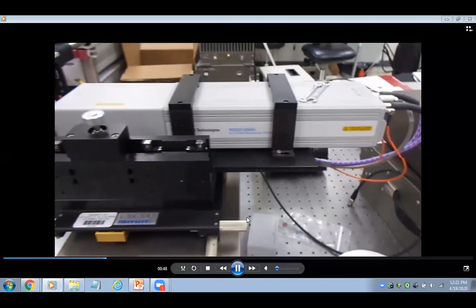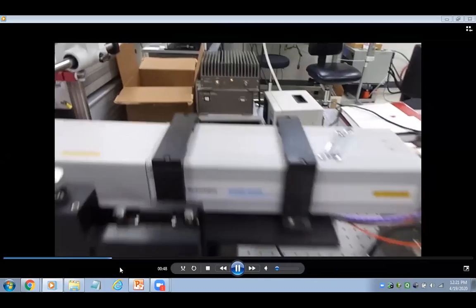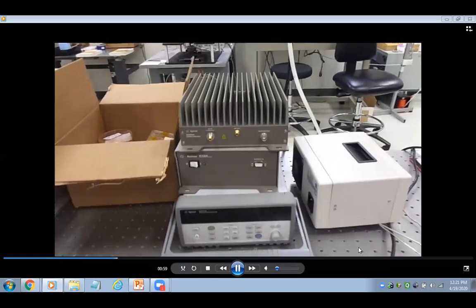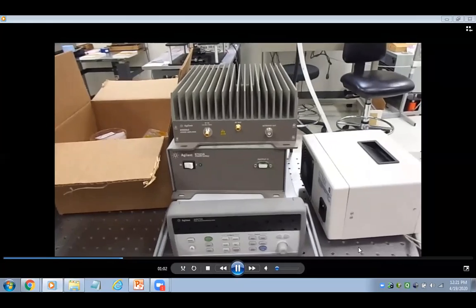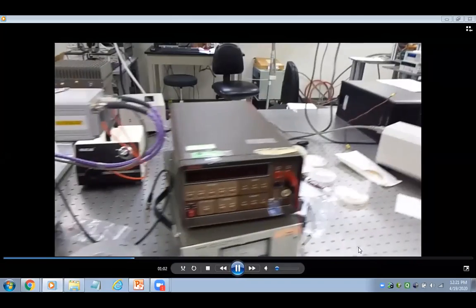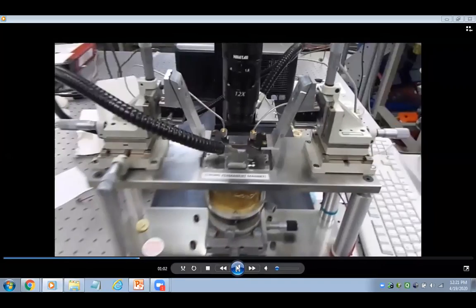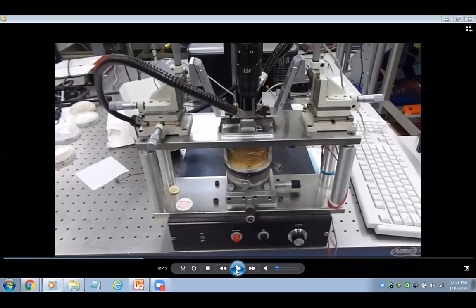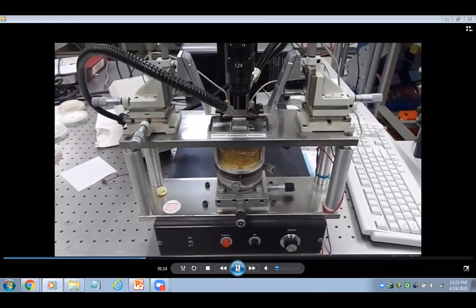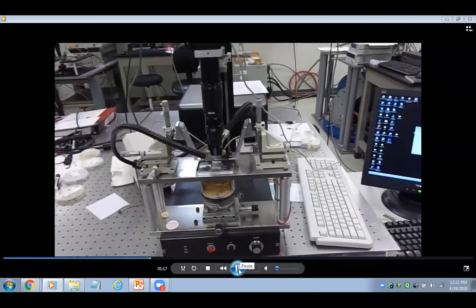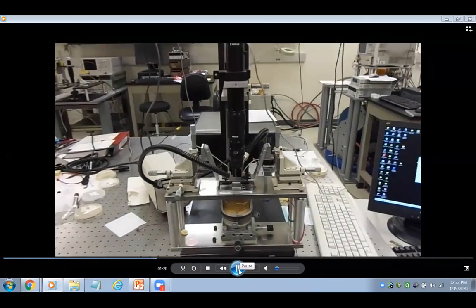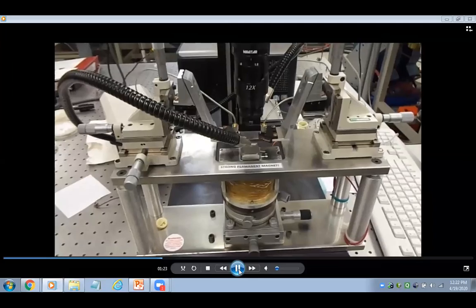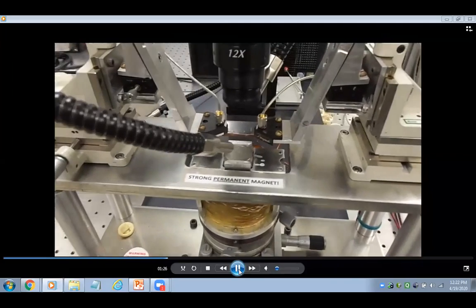Here is another side of another bench. A few instruments can be hooked up. You cannot do the hooking up yourself, you have to take help from someone at the other end. So this is another system you can use at a probe station, and you can put the sample or the device here, and land the probes by use of the microscope. These are all connected to the computer here, which has a LabVIEW program and also TeamViewer to control it. After connecting to this, you can do your measurement.